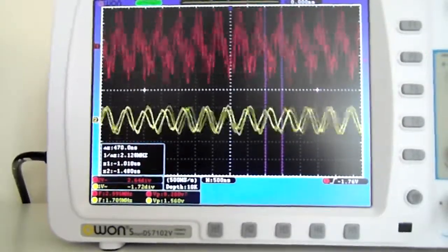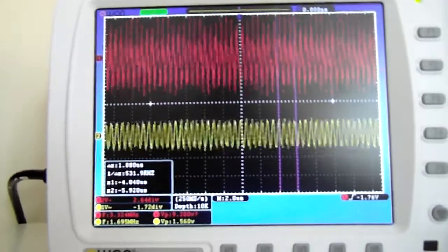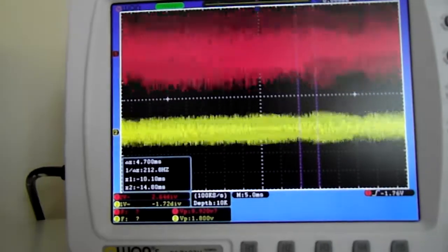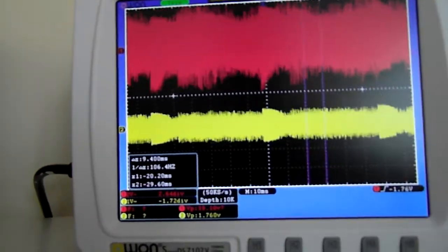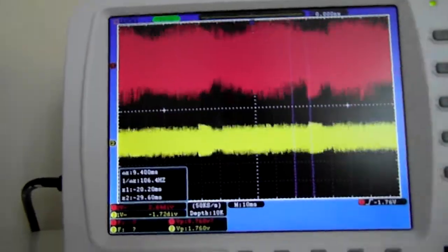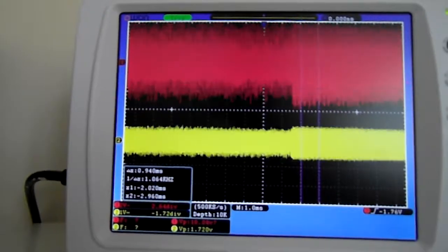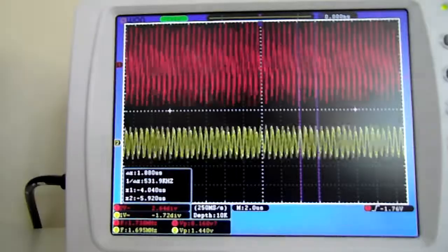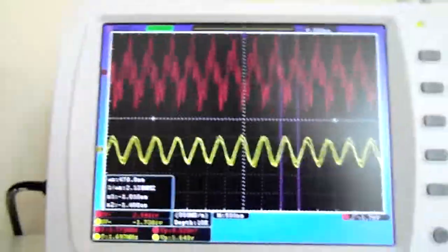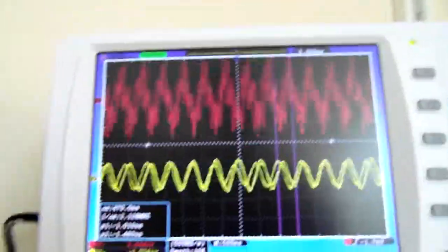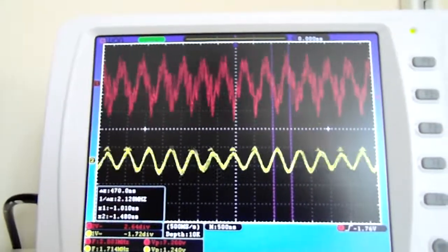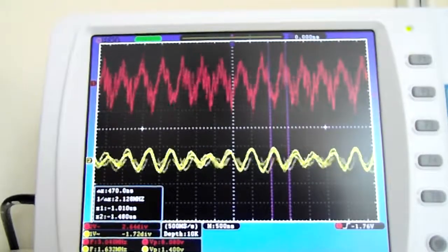Yeah, when it's really shaky like that, what I can see is this low frequency interference because it's shaky. It's not the digital sampling noise. I've checked with the analog oscilloscope. It still appears there. So it means it's picking up some ambient energy which has the low frequency. So that's the 1.7 megahertz area. It often appears. Now I'm going up the frequency,